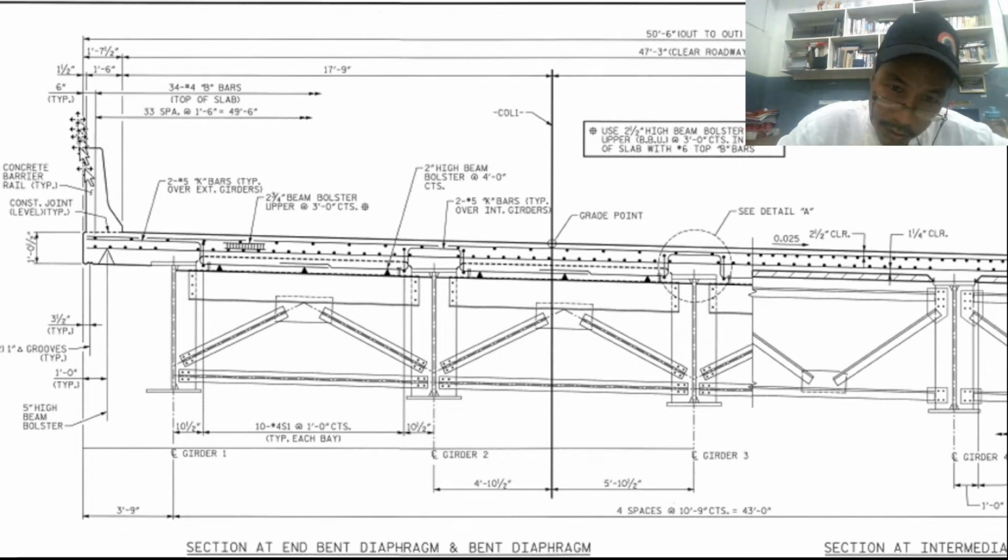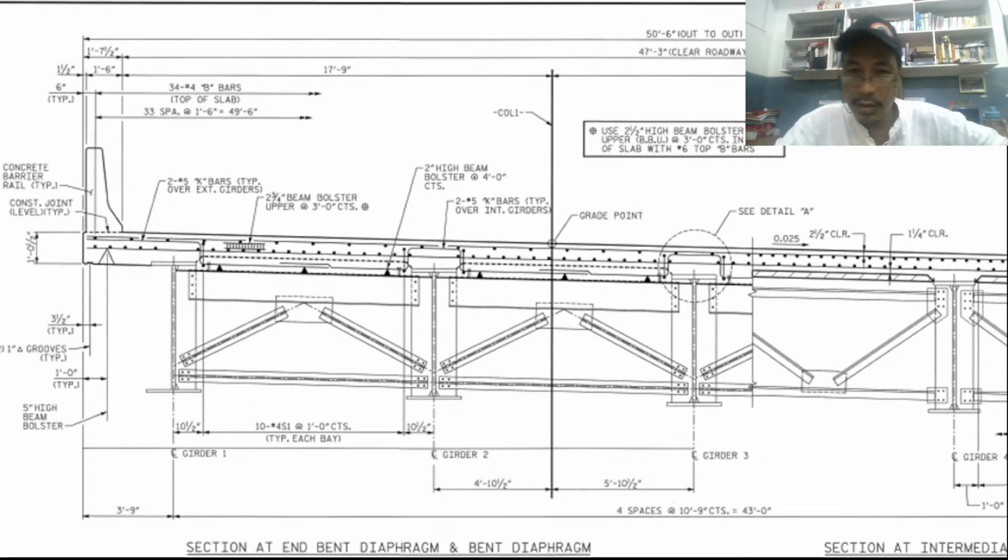What is that 1.5 inches? So the concrete barrier is set back at 1.5 inches. Okay, so there is a very small setback, 1.5 inches. So the parapet or the concrete barrier here, there is a 1.5 inches setback, then 1.5 feet dimension of the concrete barrier, then the clear roadway. So exactly our computation here. So we are correct in that analysis.